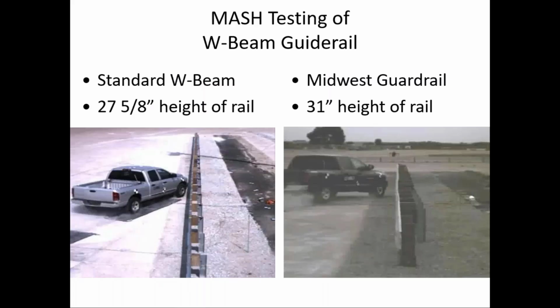We want the occupants in that passenger compartment to not have to worry about several inches of crush into the compartment or something like that. So look for those things as you watch these tests. And the other thing I would note is that these are both W-beam guardrail, semi-flexible devices, so they should deform around 3 to 5 feet. So kind of keep that in mind. Do they deflect more than, say, 5 feet or less?